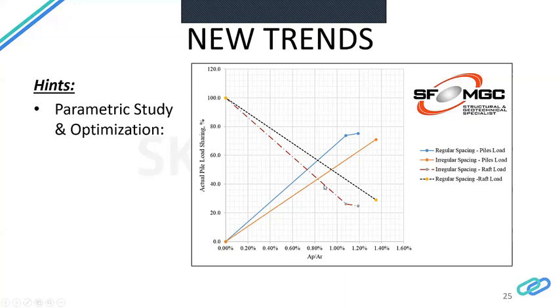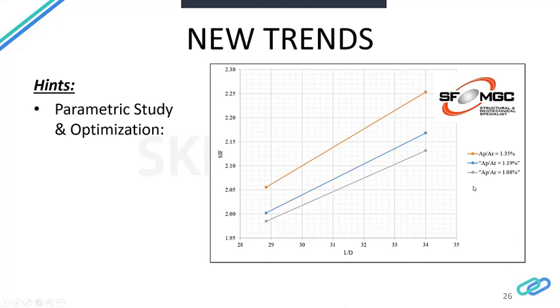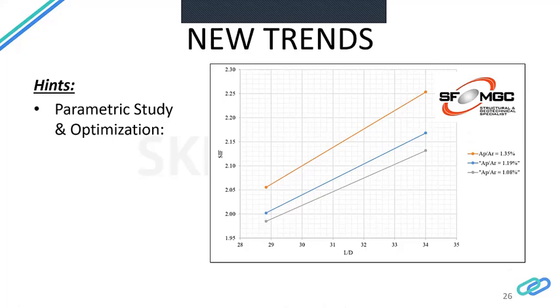So you will see the differences in the behavior while increasing the number of the piles, and how the piles attract more and more loads compared to the low number of the piles. Similarly, you have different numbers of the piles. Those three colors represent the least number, more piles, and the maximum number of the piles. And this is the settlement improvement factor, which is the settlement improved from your raft foundation case in the piled raft foundation system. And you have different lengths of the piles.